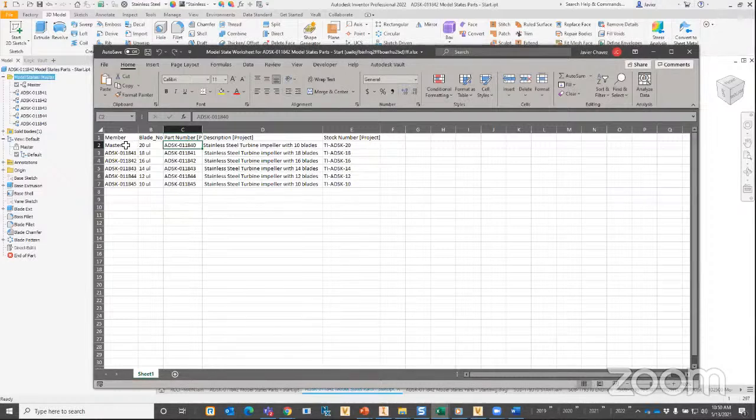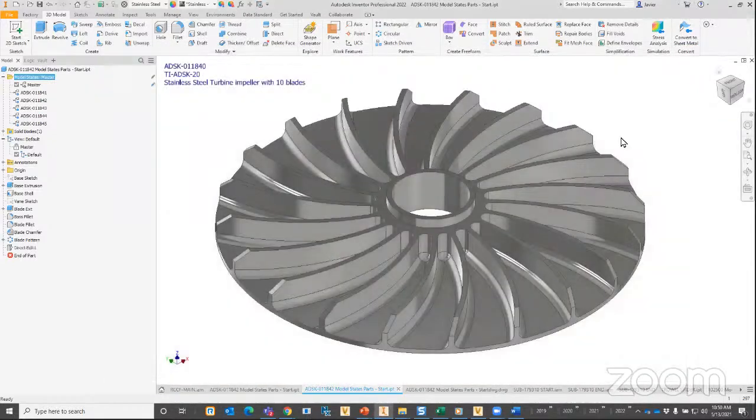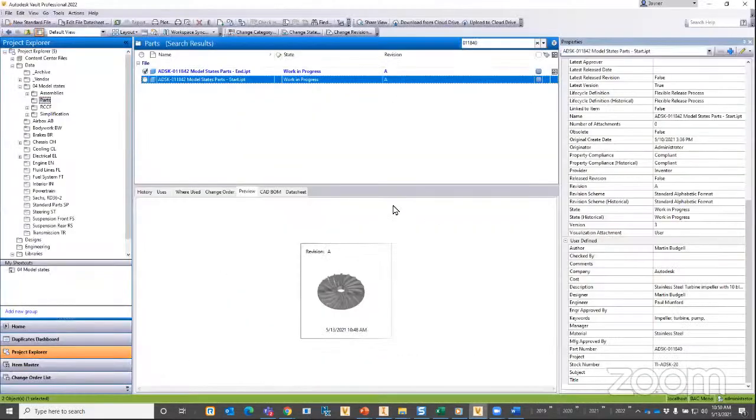Or maybe having the master row show all the possible part numbers. Okay, so just be aware of that. And if you actually have to have different part files because that workaround doesn't work, maybe you're going to work with iParts and iAssemblies.